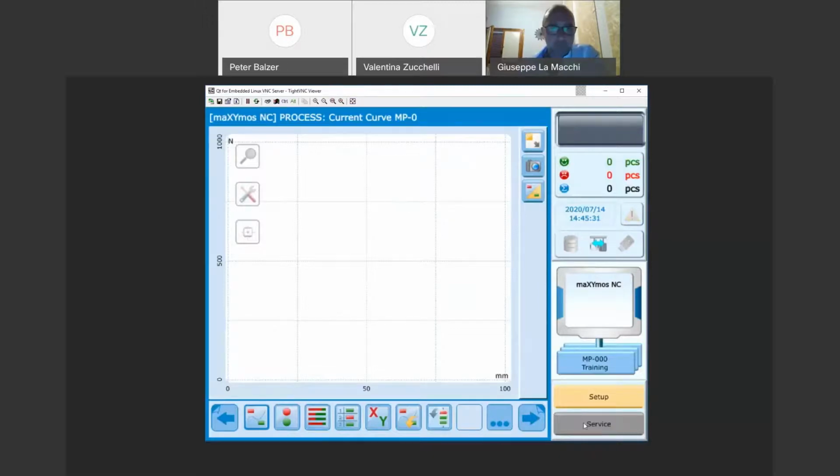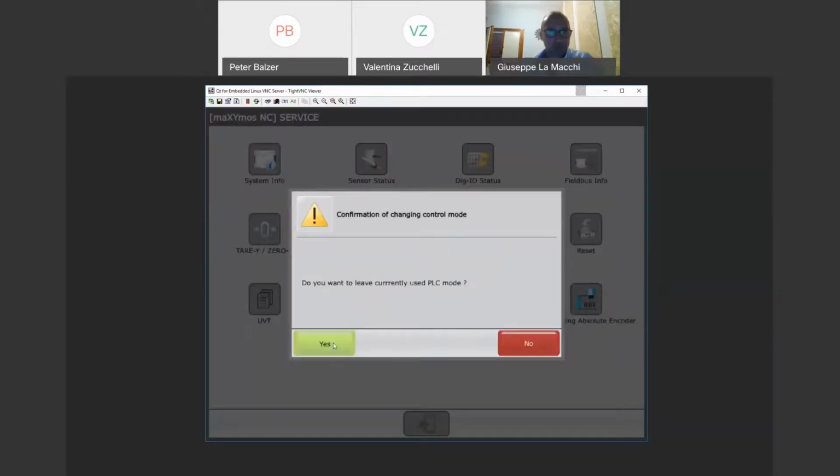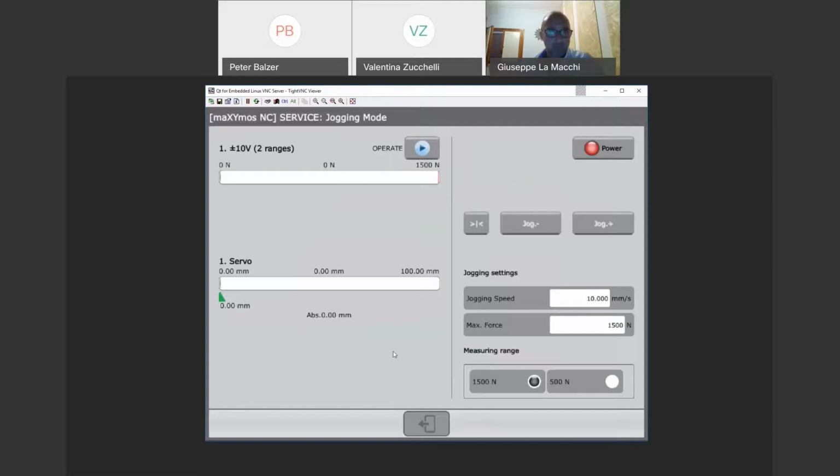Okay. So before we enter the sequence editor, I would like to show you how you figure out the positions you need to type in inside of the sequence editor. Generally, if you remember that slide at the beginning, we need 3 different positions. The first one is the home position, which can more or less always be 0 millimeter. Then we need the idle stroke position, which is always before we reach the part. And then we have a joining position to reach, for example, a target position, or if you want to shut off at some specific force, it should be oversized a little bit.